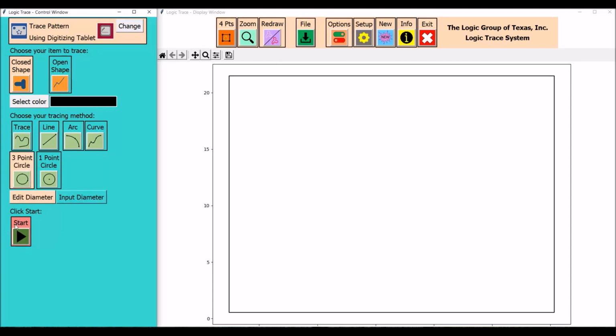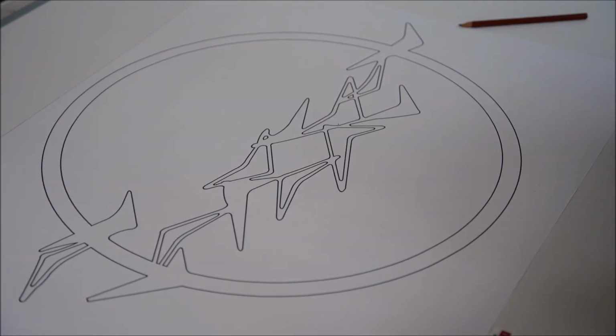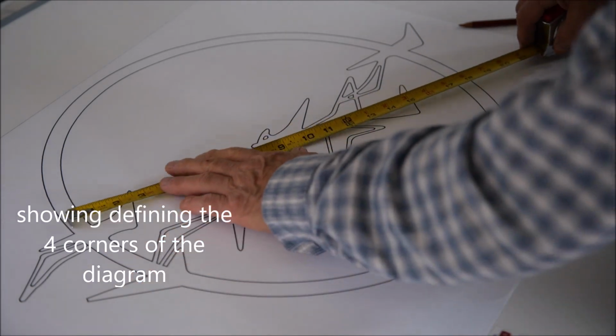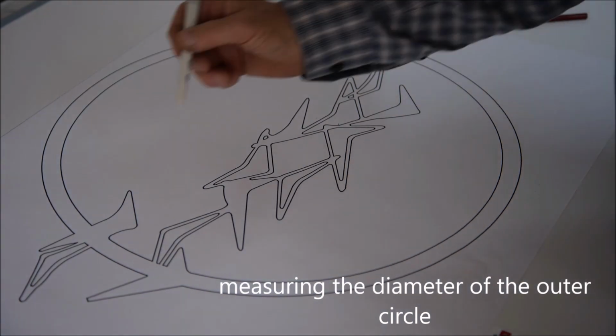My next selection is the circle command. The circle command is really neat because the computer echoes back the diameter, gives you a chance to override and input a different value if it's a bit off. I use a tape measure to check the diameter. All you're touching here is 3 points on that circle.